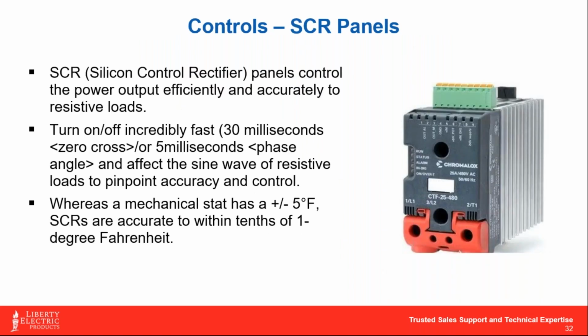This is my favorite one, the SCR panel. I really like solid state relay based controls. The easiest way to describe these is that they turn the heater on and off so quickly. You're basically playing with the sine wave, the energy wave of electric, to affect the current going to the heater itself. In layman's terms, it's almost like having a light dimmer in your dining room, where you can either make it bright and full power, or you can twist it down to just dim and barely on. An SCR controller has that type of range to it.